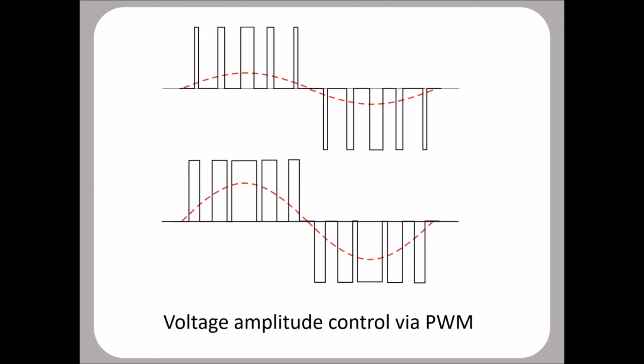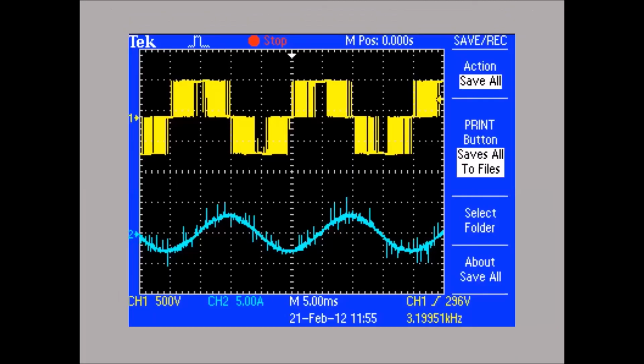You might be able to play around with it with a hi-fi system, but not for real power levels. So it's really astonishing. It's interesting when you look at what you get on an oscilloscope. Those voltage waveforms at the top are supposed to be the best we can do to make a sinusoidal AC waveform. It looks pretty awful, but actually the induction motor is such a tolerant beastie that the current, the lower waveform, as you can see, looks a lot more sinusoidal. It filters out most of the high frequency nonsense, but they're still pretty awful waveforms.